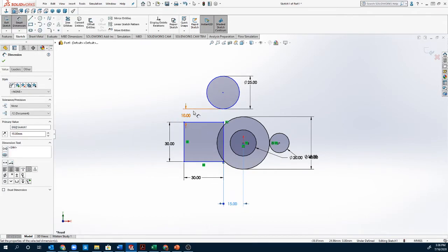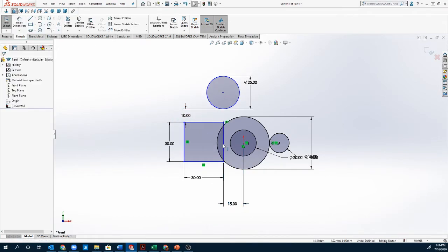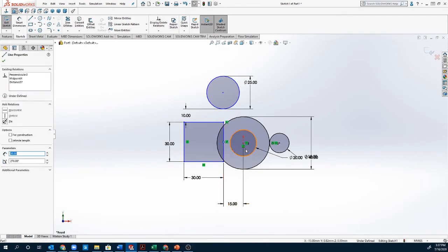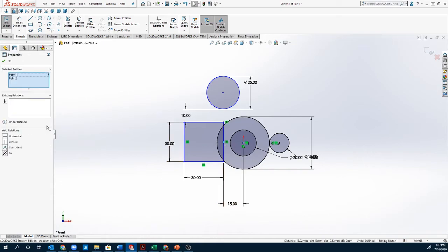And then we can say, okay, so where do we want this? So if we go on this line here and we scoot along it, you'll notice that I have a little yellow box that shows up. If I press the control key and click on that little box, and then let's say click on the origin, I can say horizontal, for example. And if I do that, now it's guaranteed to be the midpoint of this line to be horizontal with the